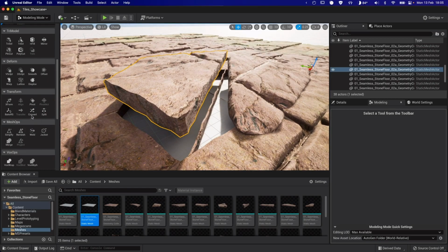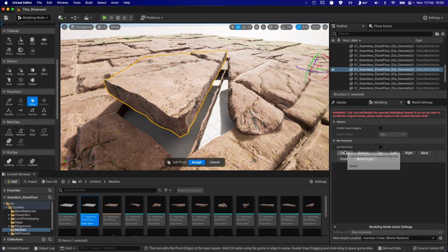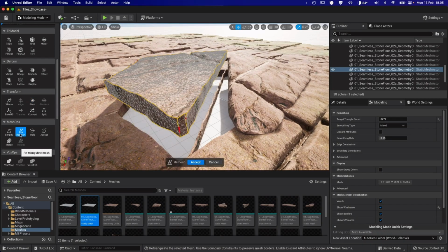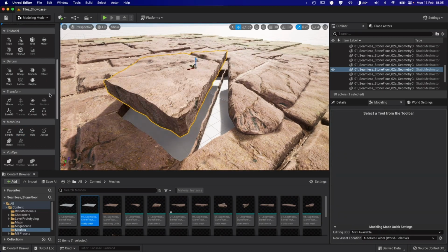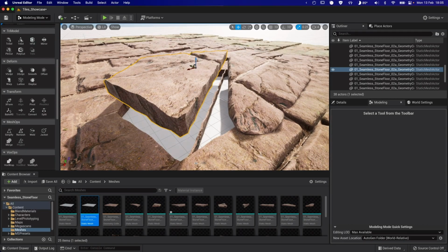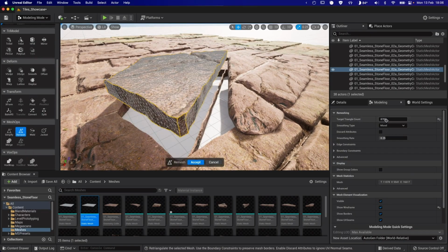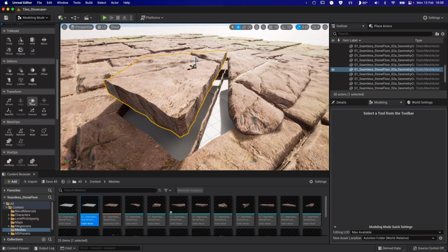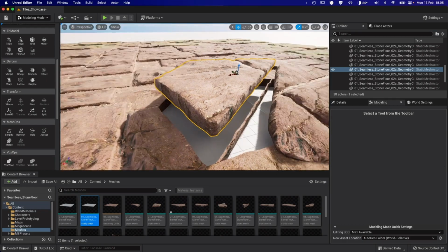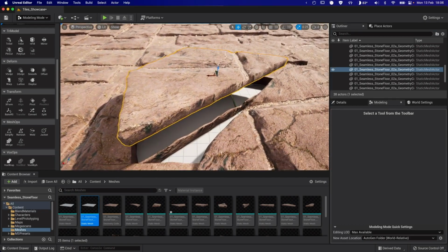First thing, change the pivot to be in the center, do a remesh, and now you can see there are some red spots. Those are holes in our mesh. Just select them all and click accept. Then we're gonna remesh, like I said, 20,000. Seems like a good amount. Do a smooth so we get some smooth edges. And I think this piece looks good as well.